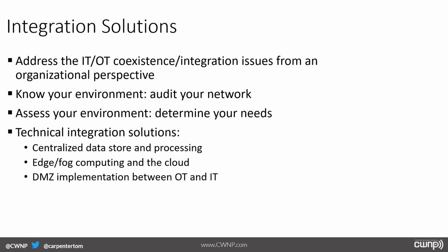So check that out. And then finally, there may be the need for a DMZ implementation between OT and IT based on some of these conflicting security policies that might exist. We in IT may be allowed to do some things that OT is not. And we may not be able to gain any type of agreement on changes in either our or their policies. And so the only solution might be that there's a DMZ between us. And then in that DMZ is our data aggregation point. So we can put IT data into the DMZ and OT data into the DMZ.